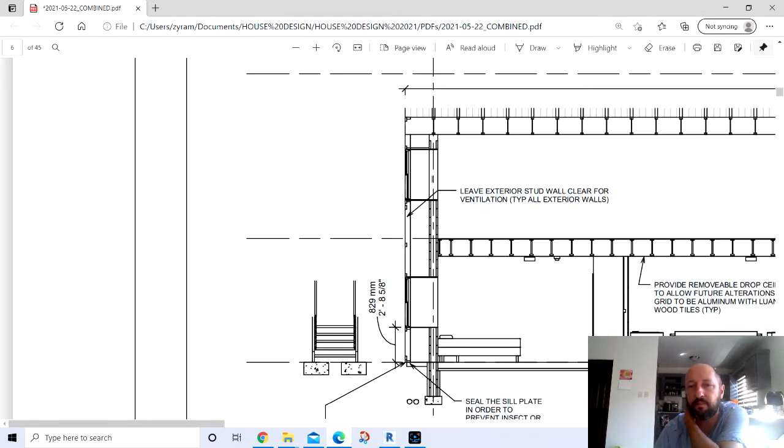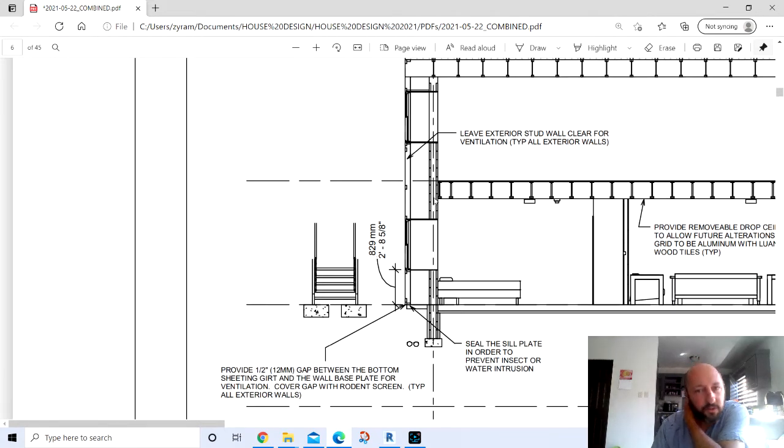So I guess I probably should have covered that a long time ago, but the ideal is to have the interior thermal mass and then exterior insulation, and in order to protect that insulation, I've got metal siding and a stud wall to protect that insulation.